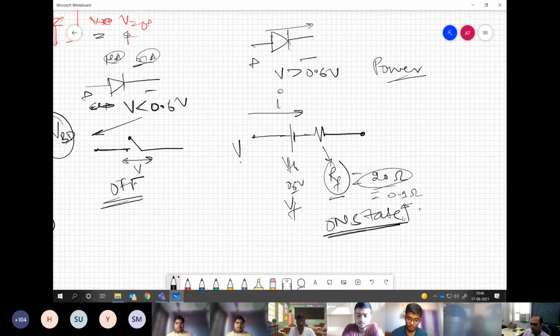Understanding my point? For diodes used in our digital circuits and other applications, where we already have huge resistances in the circuit, let's say of the order of 10K or 20K, this 10-20 ohm is actually nothing in front of that. So it can be very easily ignored. Here the current requirement is also a few milliamps. So we are not carrying a lot of current, and the power loss is also within the limits of the design. So this is how these values are. Getting my point? Yes or no?